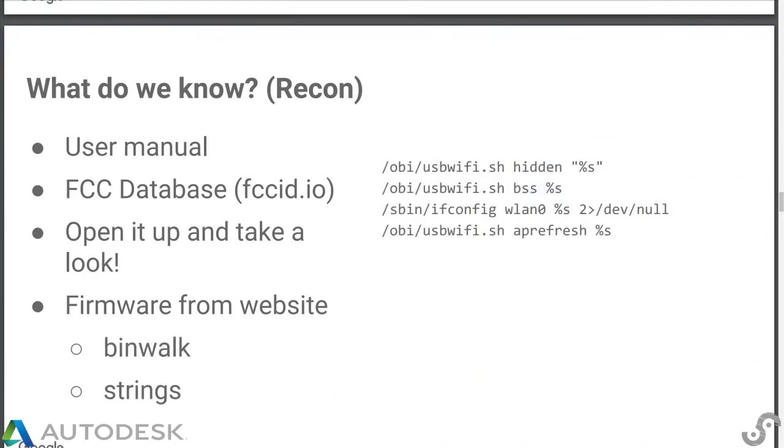So from the firmware, there's a wonderful tool out there called binwalk, and what that does is it goes through a binary blob and extracts other known file types from within that binary blob, and it gets you all of these files out of it, and it'll even find compressed files that are inside that. So like the firmware might be a GZ with some special header on it, and it will find this, extract the gzip, and give you the raw file.